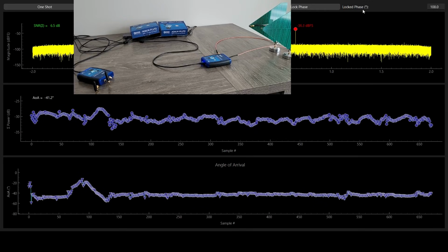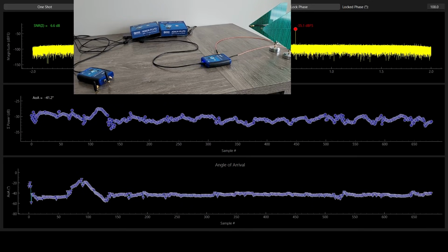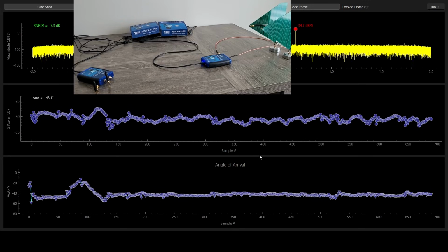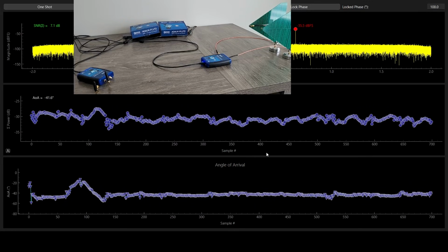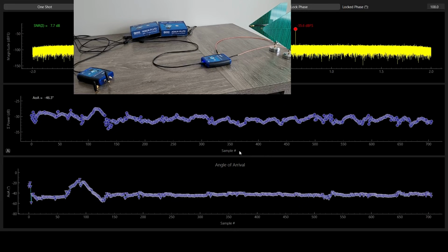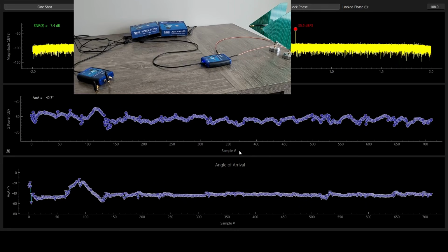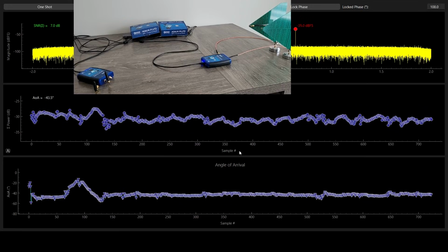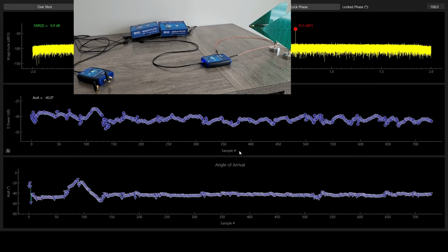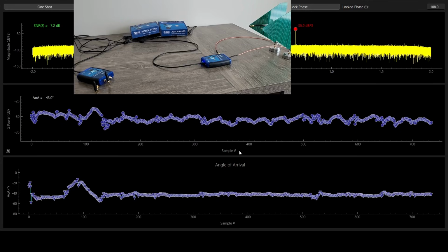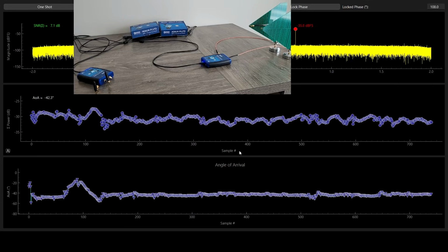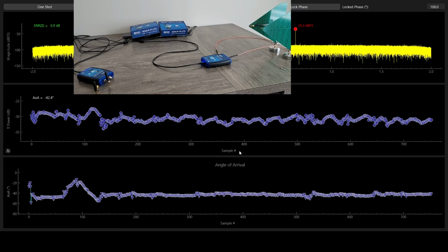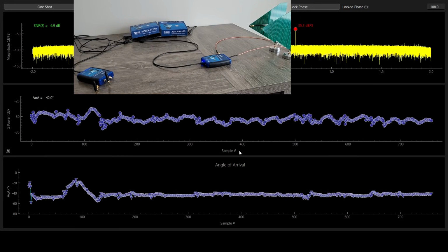Basically, in the beginning of the video, I showed we can continuously sweep the TX phase and find the received power and the angle of arrival. And basically that is something that needs to be done in a beamforming system when both TX and RX have a phased array. We need an initial alignment, and that initial alignment can be done through sweeping the TX phase to find the point that the maximum power is received, and we call that now the beam is aligned, right?